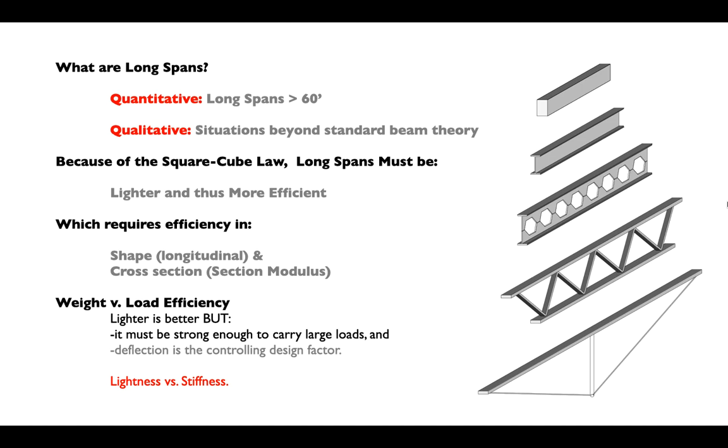And if you want to push this to an extreme, we could do something called a king post truss, where we really separate the chords into one long tension element, a cable in this case, and one compression element, right? Here's a flange, and then instead of the triangulation of the truss, we just have a single chord, a single king post that creates that distance between the tension element and the compression element.